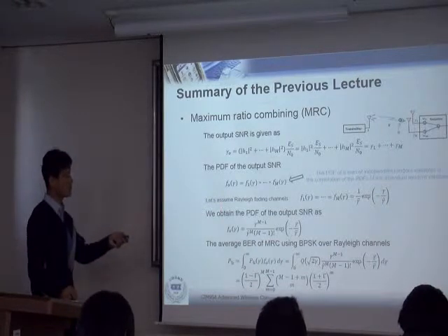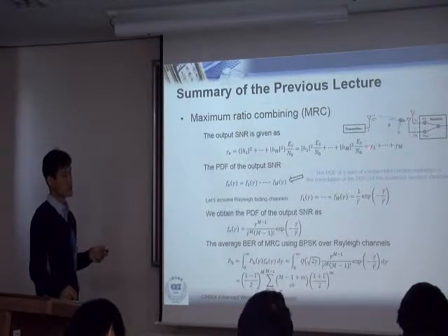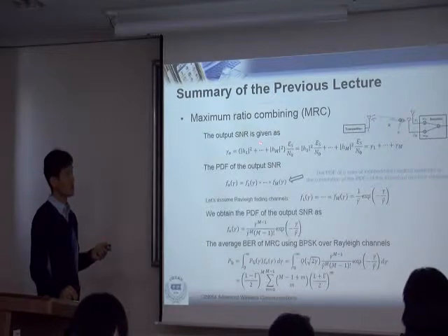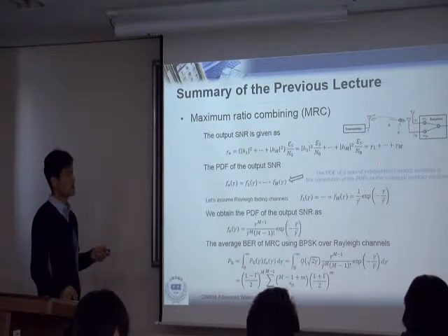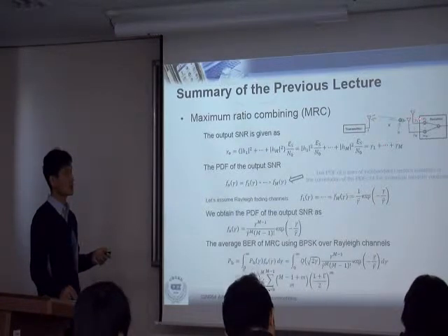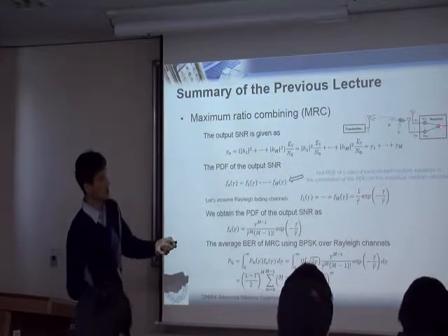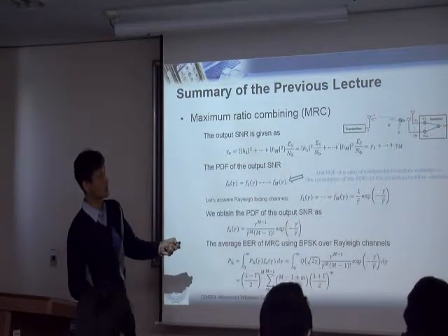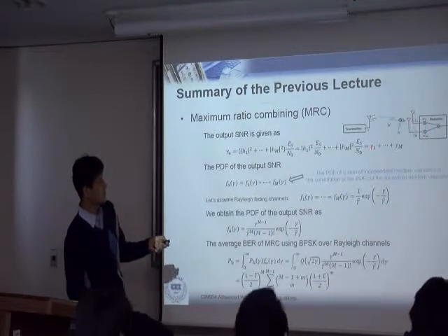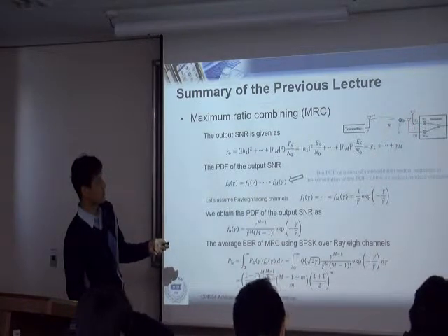We also talked about this one earlier. Now, when you use multiple antennas, for example, in the receiver, there are several different ways to run the receiver. If you use MRC, that means you basically combine all the SNRs. Okay, that's what you can achieve. The output SNR means the SNR right here after the combining. After combining, what you receive is gamma 1 to gamma m, the addition of all these. What that means is you are basically adding all these SNRs.